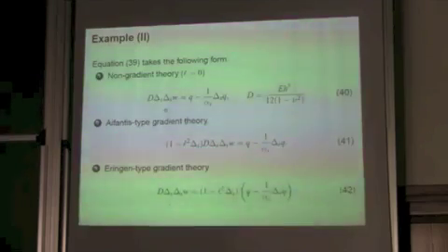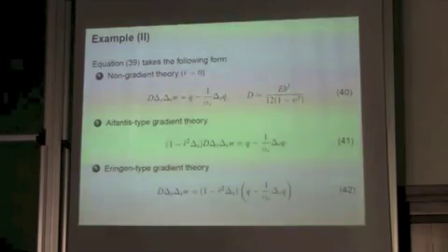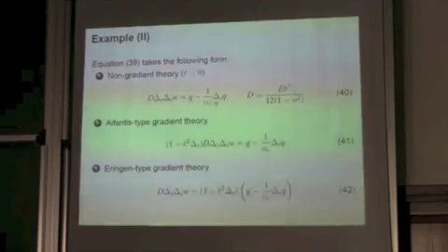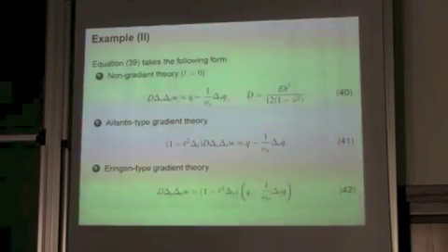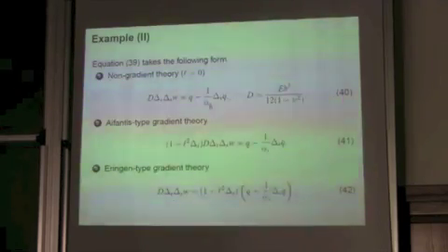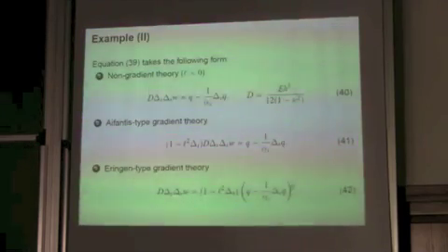And now, in addition, we have additional elements. If we have a no gradient theory, but of micropolar type, that means the scale factor is equal to 0, then we have only this additional contribution, which is related to the non-classical part. This is a classical bending stiffness, but you have here the additional influence from the shear, which is presented by this element.